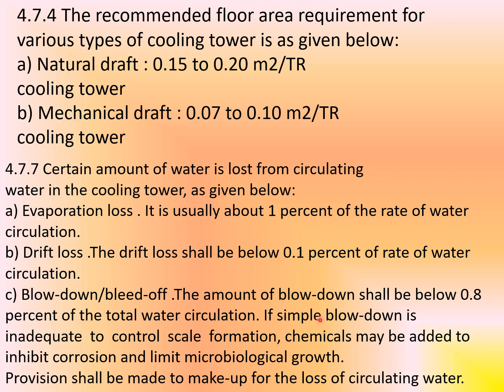If simple blow down is inadequate to control scale formation, chemicals may be added to inhibit corrosion and limit microbiological growth. Also, provision shall be made to make up for the loss of circulating water through a makeup water tank.